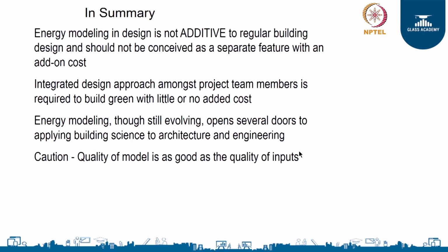So to summarize, we have tried to see how energy modeling should not be treated as an additive to design. It should be part of the integrated design, and it should go along with all the phases of the building life cycle, starting from pre-design to schematic design to detailed design, all through construction, and see how your building performance changes as you elaborate the design. It's extremely important, and on top of that, you continue to use this model during the operations as well, and retrofit or calibrate your model continuously to the actual energy performance based on utility bills that you get during your operations.